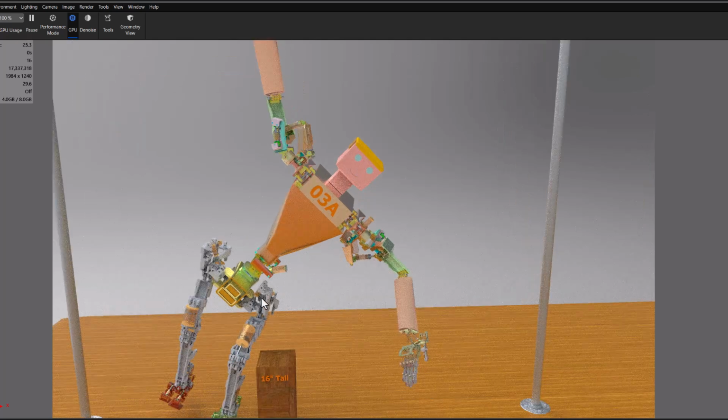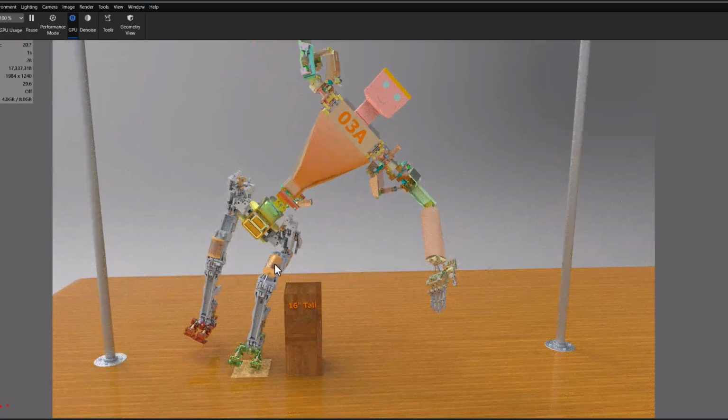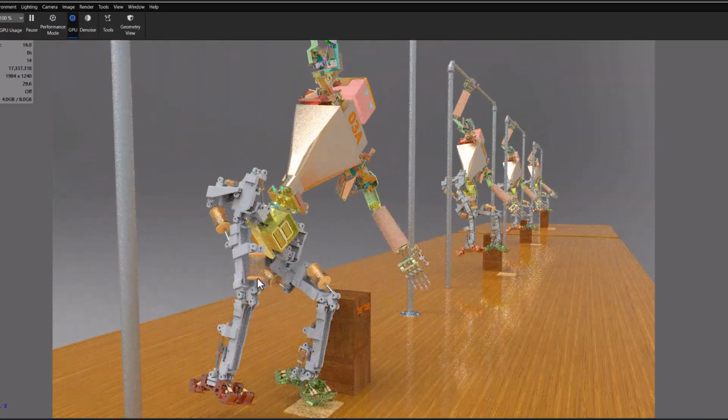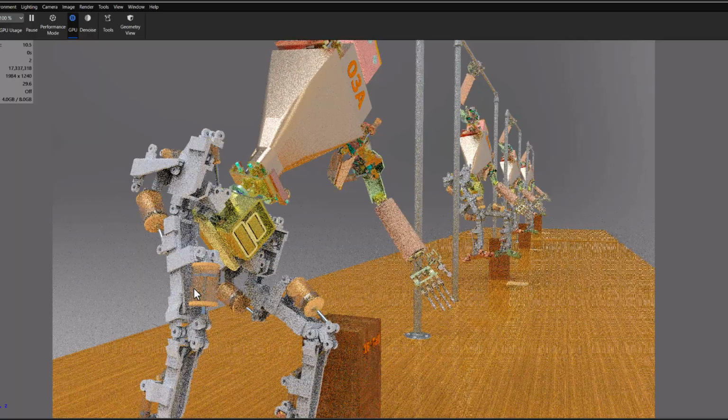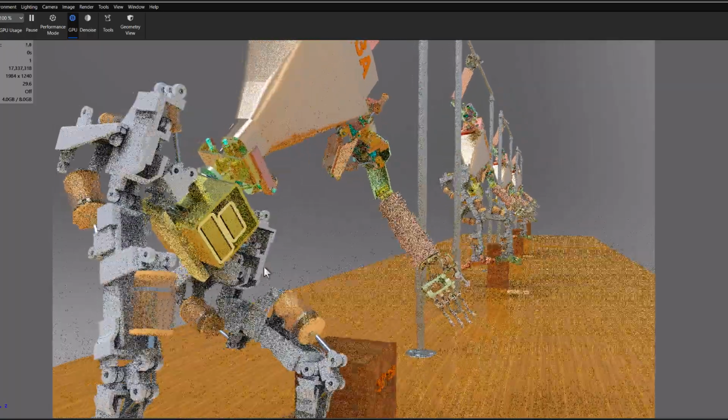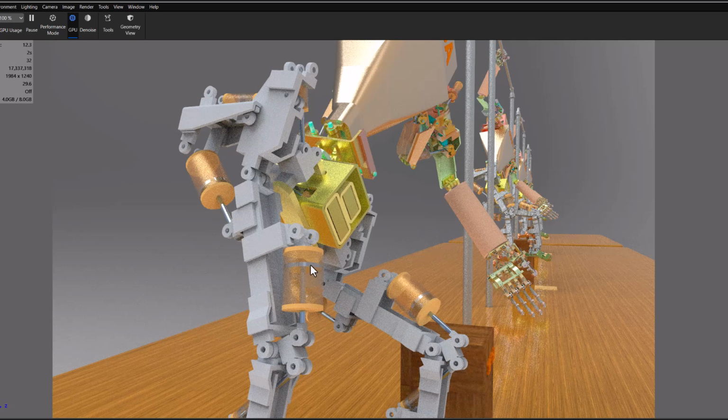And one of the reasons why there's been a resistance to hydraulic cylinders is because of the nature of how hydraulic cylinders work. The way a hydraulic cylinder works is there's a pressure differential across the piston head. So if there's more pressure here than here, this will go that way. If there's more pressure here than here, this will go that way. The only way that works is that the outer circumference of the piston head has to be very closely approximated to the inner circumference of the hydraulic cylinder.